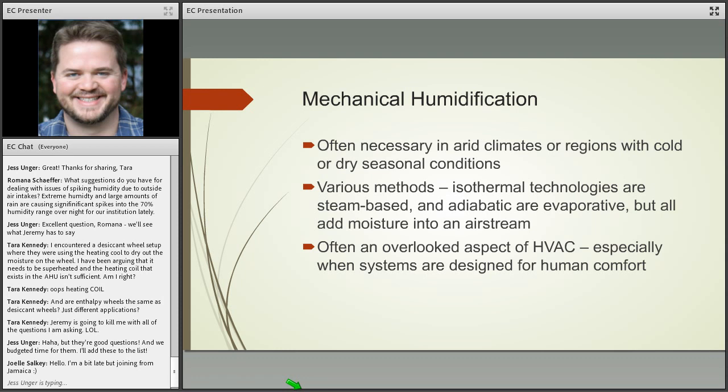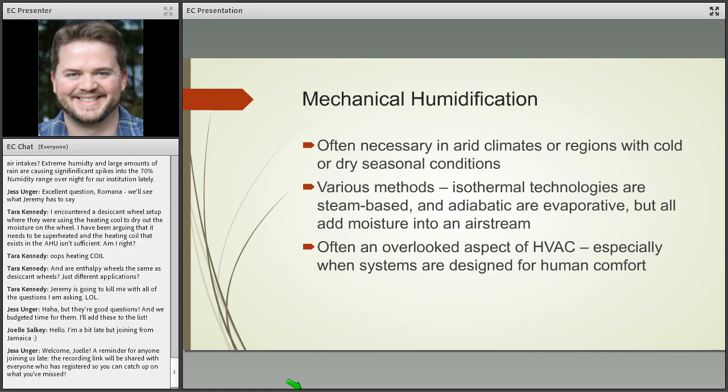And for spaces that were originally designed looking at human comfort environment conditions, that 70 degrees condition, where we're not really thinking about moisture control, if the humidifier isn't there, then you're not going to be able to control relative humidity either in the wintertime or in a dry environment. This happens in a lot of older buildings, a lot of repurposed buildings, where you walk in and if you're using environmental data logging, you discover pretty quickly that in the wintertime, you may be able to manage your temperature okay. You may be somewhere between 65 or 70 degrees, somewhere in that range. But all of a sudden, you notice that your interior relative humidities are dropping down into the 15%, the 10%.